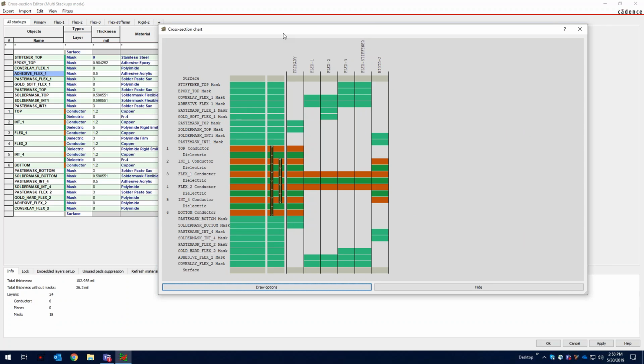So as you've seen, when deciding on a stack-up, there really aren't any hard, fast rules as to how many layers constitute the best stack-up for high-speed designs. The decision is going to be based on cost and on materials and the needs of the design. Work very closely with the board fabricator as well as mechanical engineers, electrical and power engineers to determine the best stack-up that's going to fit the board that you need to design. So that concludes the live demo portion of the webinar. I'm going to pass this back to Matthew.